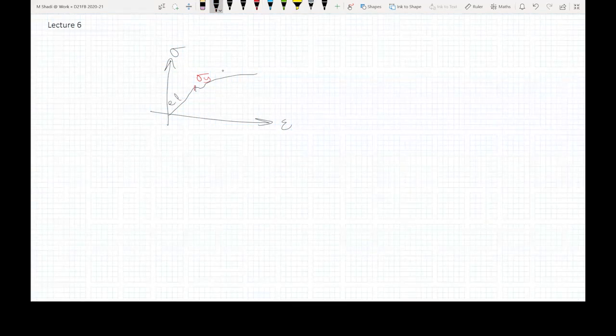So this is elastic, and then after that, you have an inelastic region. In the most general case, we say inelastic just because in brittle material, we don't have an inelastic, we don't have a plastic region. So we have just immediate failure, pretty much immediately after the elastic range. So we said that this is the point of inelasticity in the most general case, and this is how we distinguish between the two regions.